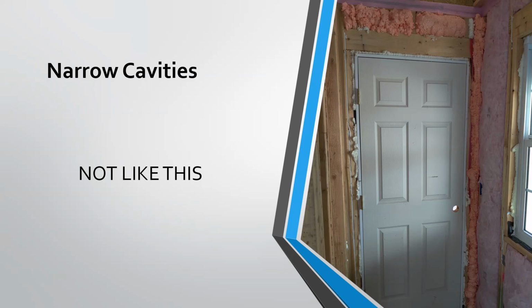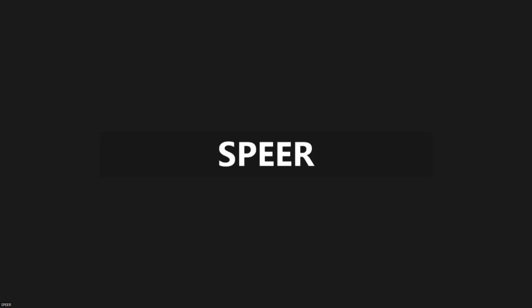In my opinion, if they don't cut it gently with a knife to the level of where the sheetrock's going to go, it's all just going to be scraped out so that the sheetrock will be installed. It will not be insulated. It will increase the heat transfer through these sections. Hopefully there's a big enough patio that it doesn't get direct sunlight. My house faces due west, so if this was my house, then that would absolutely be the wrong thing to do because it's going to be left open.